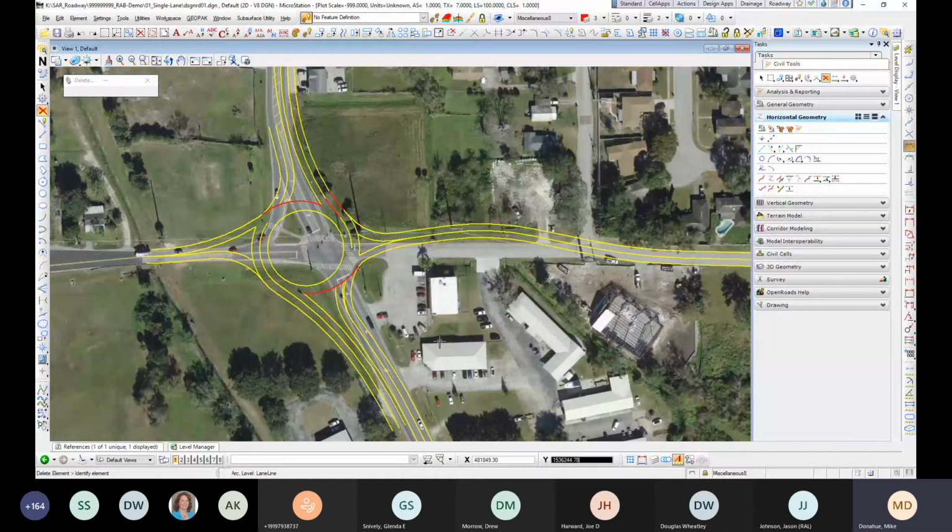It may be good to get a concept together, but no intersection is the same. All intersections are different. So, you can see this one here. I tried to pick an intersection that ultimately is going to be a roundabout. It's going to be a 1x1. It's not a 2x1 in reality, but I wanted to show something that was existing geometry for a roundabout intersection, and how you would work with it. I didn't want to select something that was perfect for the demo, because I wanted there to be issues, because there's going to be.